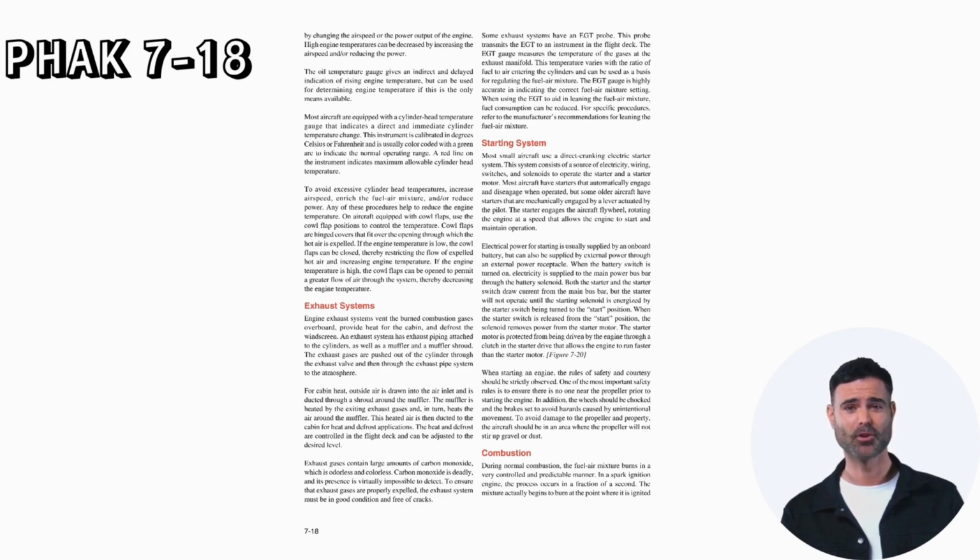The heat and defrost are controlled in the flight deck and can be adjusted to the desired level. Exhaust gases contain large amounts of carbon monoxide, which is odorless and colorless. Carbon monoxide is deadly, and its presence is virtually impossible to detect. To ensure that exhaust gases are properly expelled, the exhaust system must be in good condition and free of cracks.